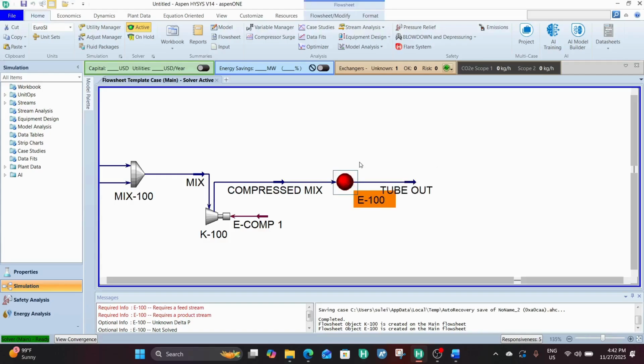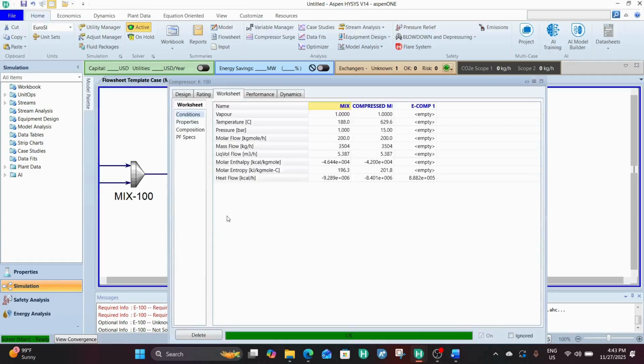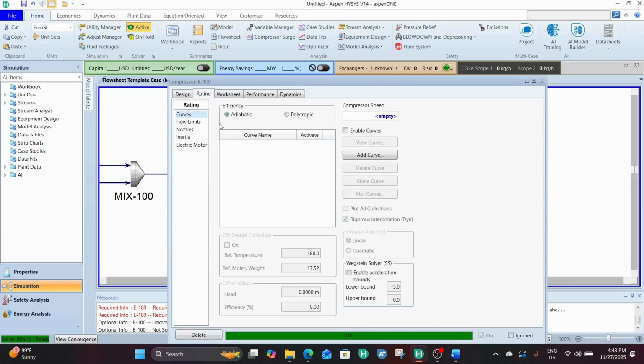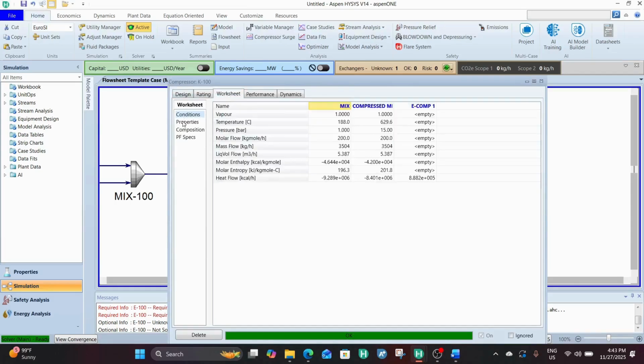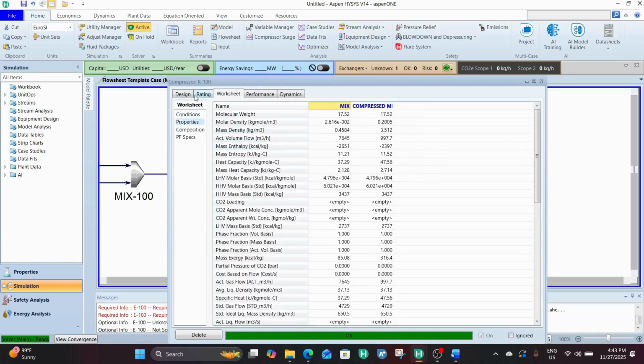It's a dark stream, but the equipment is not yet functional because it lacks values for the shell side of the heat exchanger, the shell inlets and outlets. But we're going to work on that very soon. So since we're incurring a pressure drop in our heat exchanger of 0.5 bar, we might as well increase our pressure to 15.5 bar to cover the 0.5 loss.